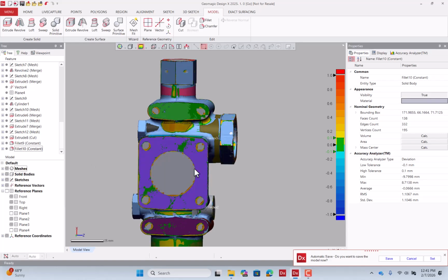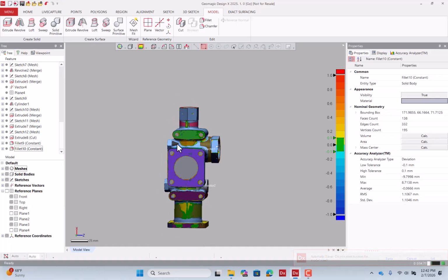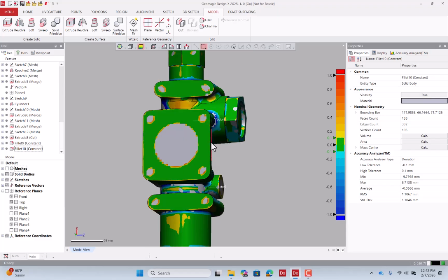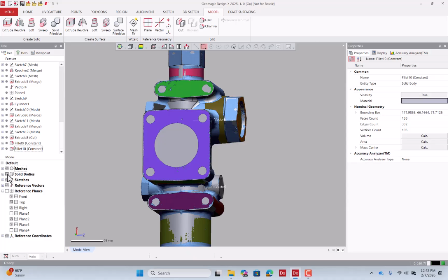And after this, you can make all the through holes as necessary. So in this particular exercise, we saw how we can use regions. We saw how we can select areas of the scan data and insert the regions. We also saw how we can select rather large areas and split those regions into smaller and more accurate regions. The regions also give us good information on what type of surface it is. It helps you identify if the particular surface is a plane or a cylinder, etc.